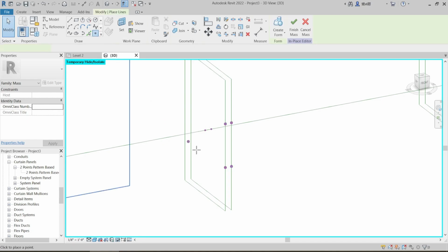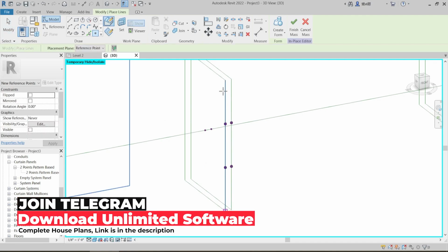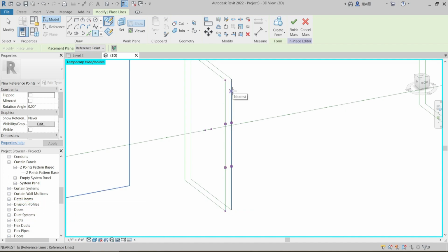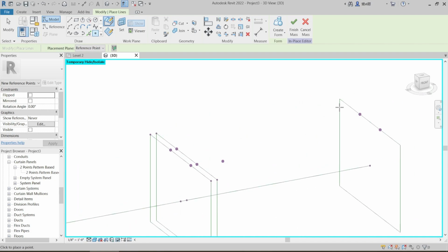So point element over to this line, SE, snap, and likewise over to this point, over to this line, and SE is showing on the bottom point only. So I'm just going to manually place it, because anyway it is snapping to that.